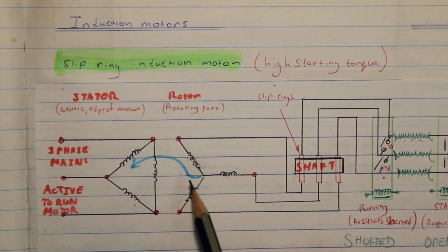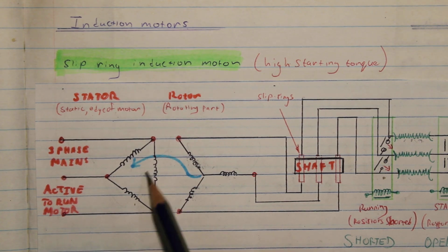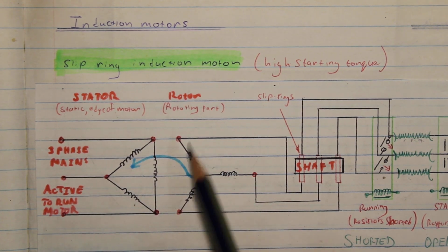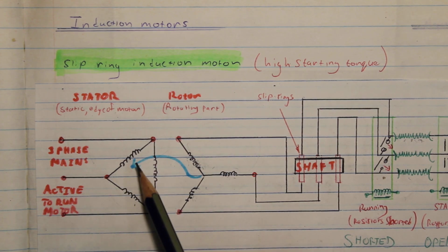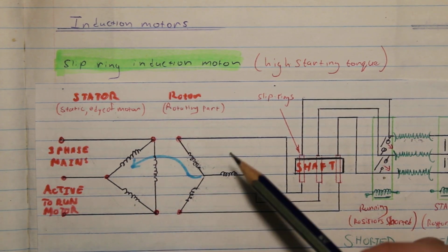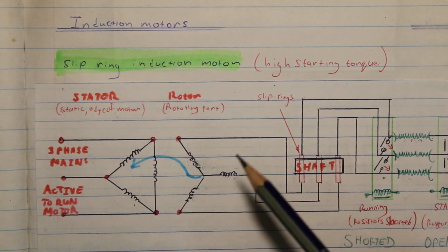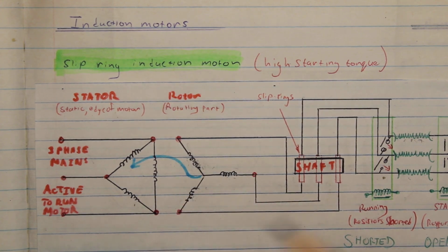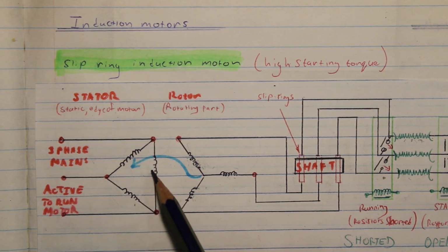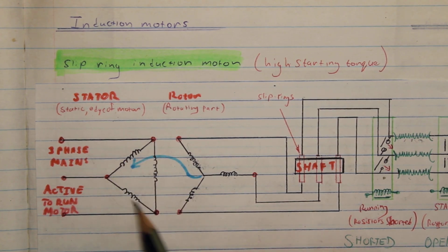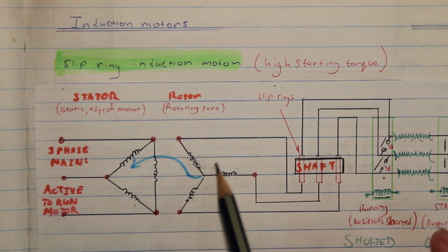The frequency of the rotating magnetic field of the stator is moving at 50 hertz, and the speed of the rotor is not. Remember, it's an induction motor, so it can't ever reach 50 hertz. It is running at 95% of this 50 hertz. All right, so it's almost there. It's 95% of the way there, but not 100% of the way there. So when we think of that, this induction motor, the only reason it can turn is because it's being cut by this magnetic field. So of the full 50 hertz, or of 100% of this field, only 5% is now cutting this rotor.